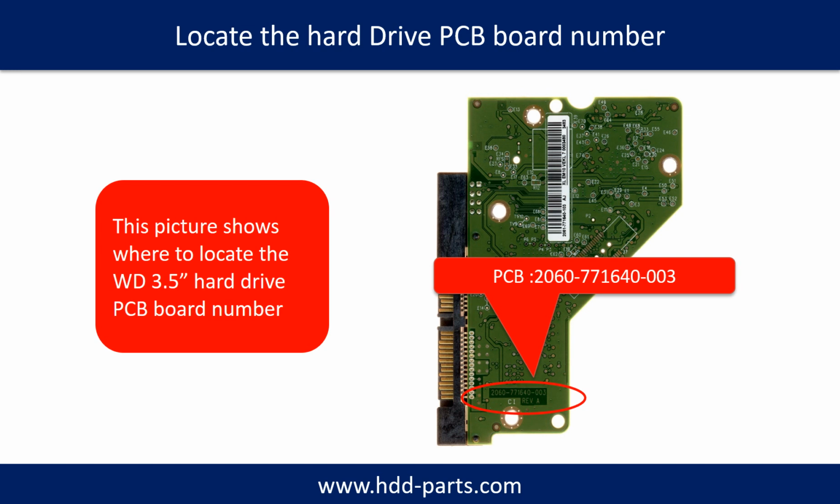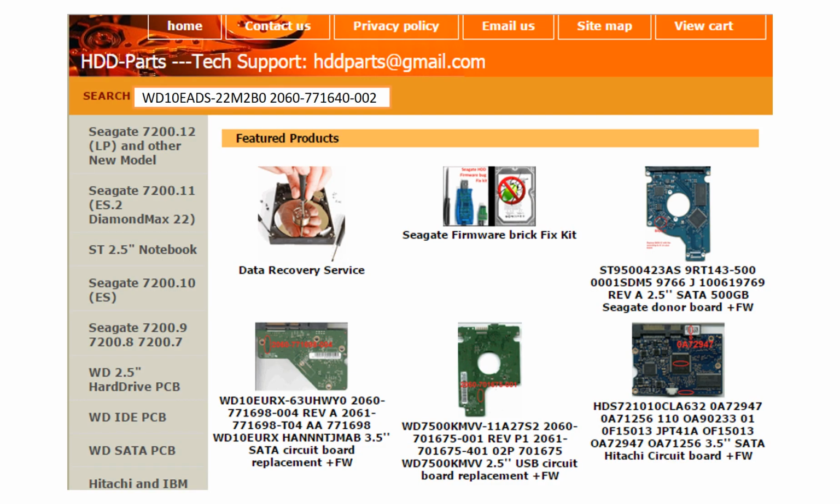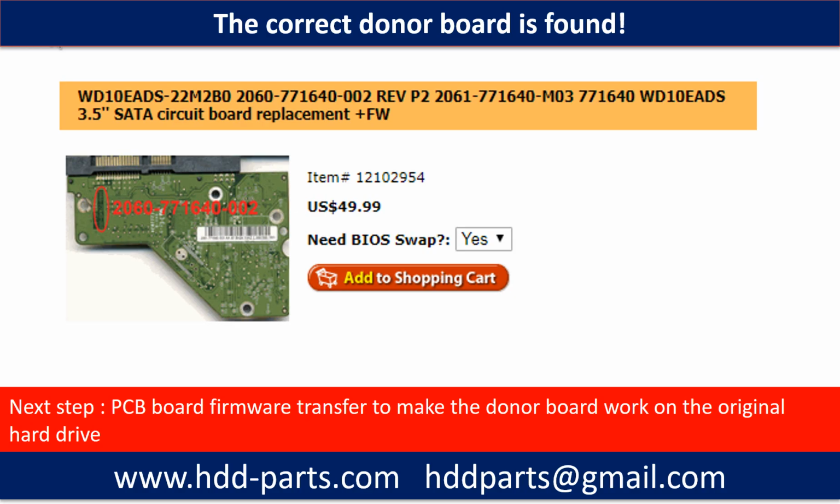You may go to hdd-parts.com to check out other brand name PCB board numbers. After finding out the hard drive model number and the hard drive PCB board number, we use them as a reference to search for the correct donor board. We found the correct donor PCB board for the hard drive, but this is only the first step. The next step is we have to do the PCB board firmware transfer to make the donor board work on the original hard drive.